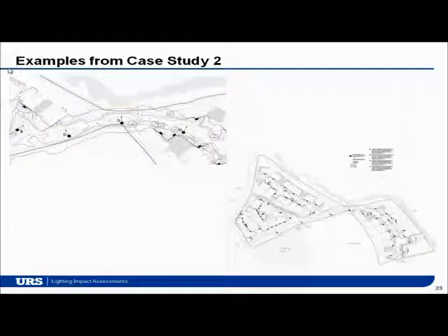This is an example of another residential development. Just to show really, on this one there's a pinch point in the site where we had to install a luminaire. It's a column-mounted installation in line with the local authority requirements. The area to the north is the sensitive area, and we looked at various options, still wanting to keep to an S4 standard for subsidiary road lighting.